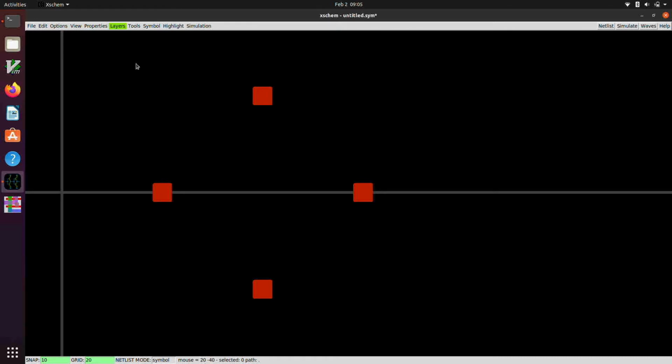I start out at 10, and now I'm going to hit L to make a line, and then you click to complete the line. So there's a triangle. I don't particularly like where that is. I'm going to go down by a factor of 2 to 5, and I'm going to select this and then hit the M key to move. And I kind of like where that is.